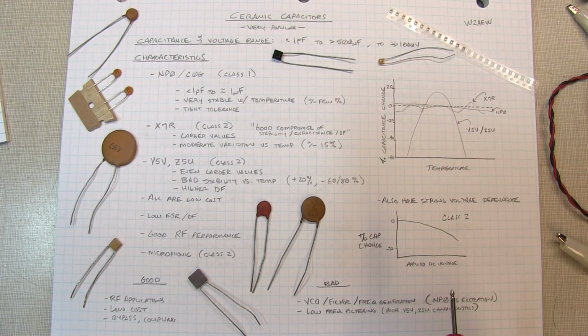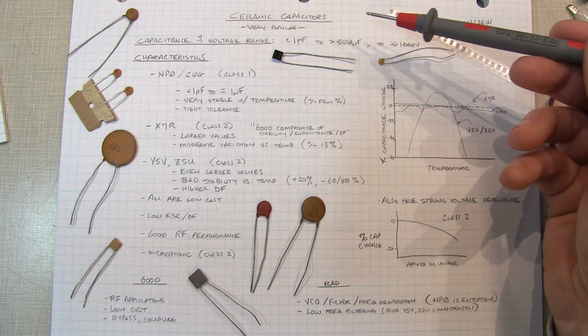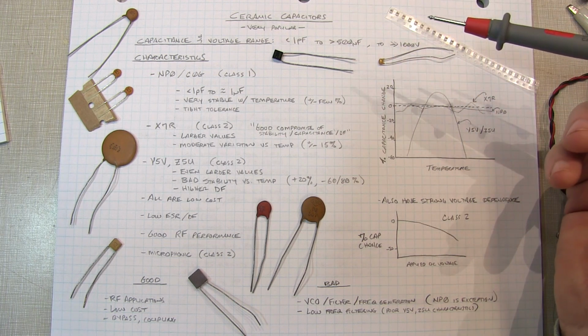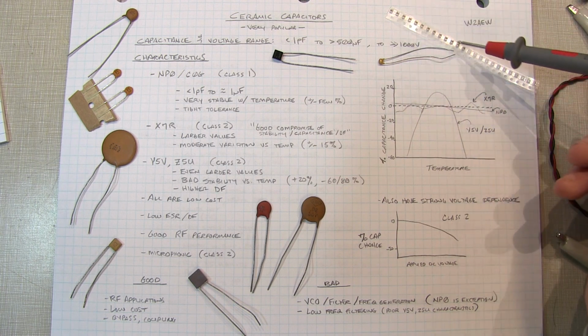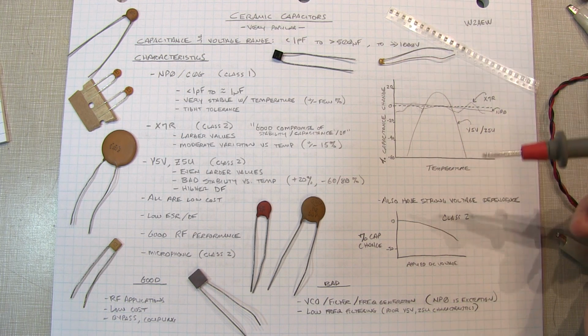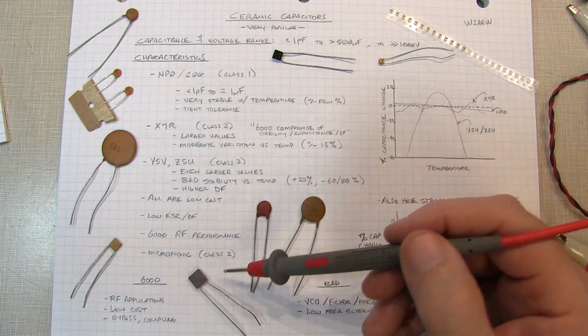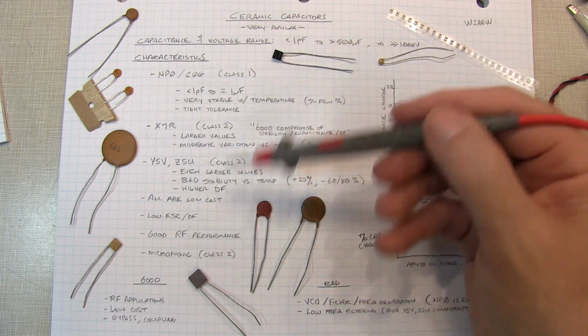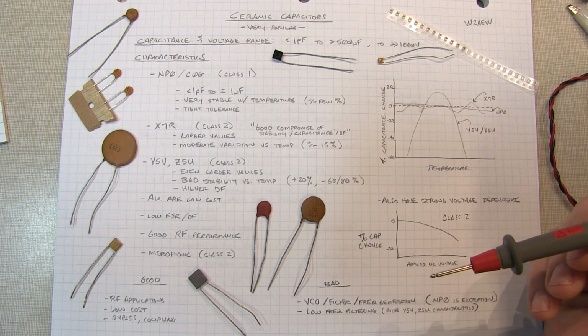Now, outside of the low-frequency power supply filtering and decoupling caps and things like that, you'll most likely find ceramic capacitors. They're certainly the most common that are out there. And with most modern electronics being surface mount, the vast majority of small surface mount capacitors are these multi-layer ceramic devices like are shown here. Lots of different package styles, from the disc capacitors to these kind of molded monolithic type devices and dipped monolithic devices like that one there.